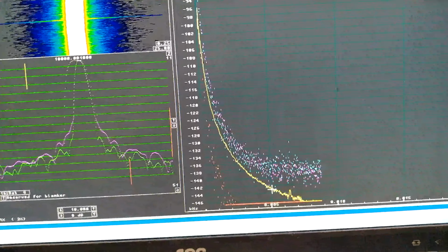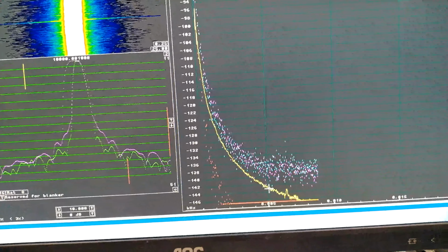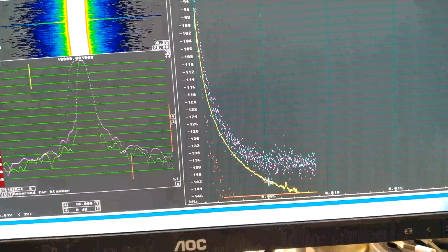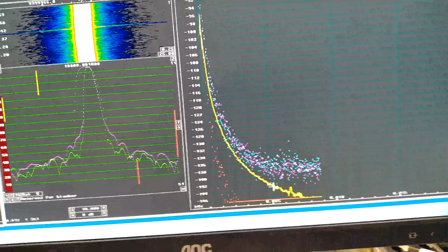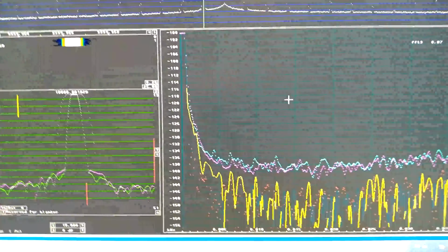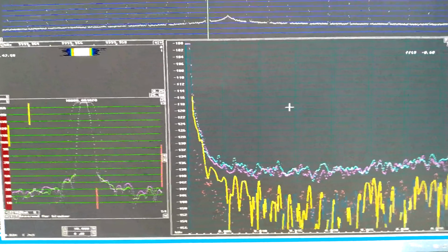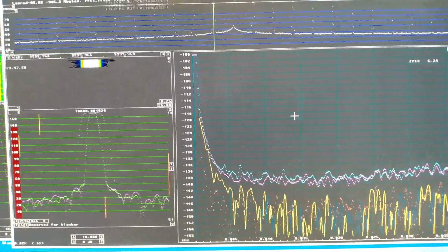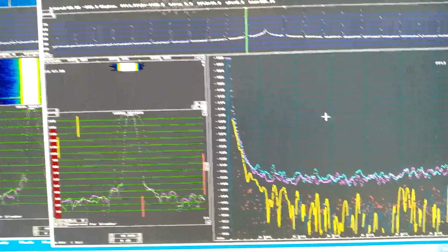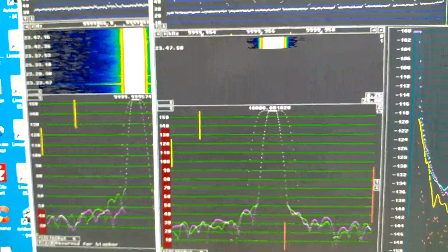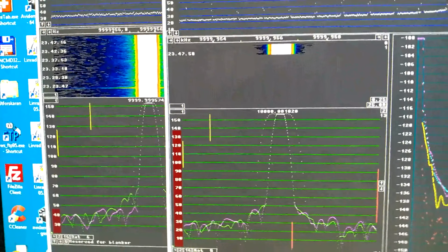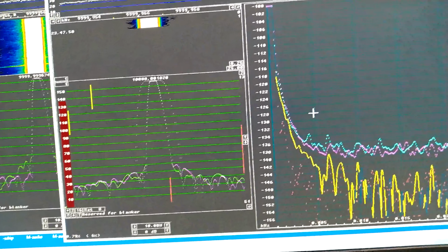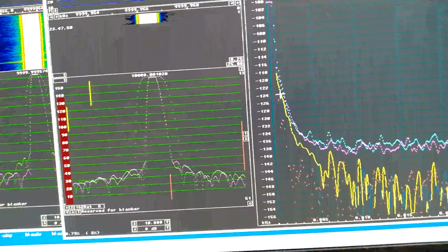At 5 Hertz I can see minus 143 with the sound card, and I don't know what will happen at higher offsets. I have set the parameters for the sound card now to get rapid results at about 5 Hertz offset. The baseband filter here is about 1 Hertz wide, so I cannot read at 1 Hertz offset, I think.